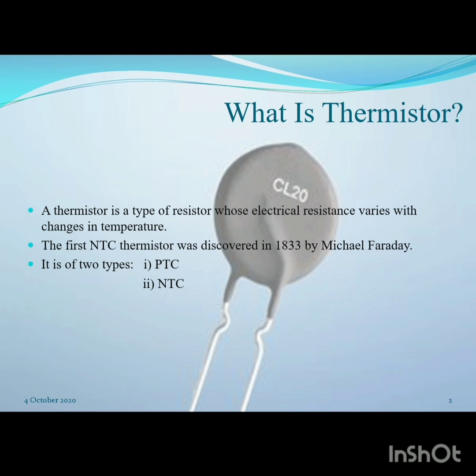A brief description of the PTC: resistance increases with a rise in temperature. It's just the opposite. This is the normal case for conductors. PTC thermistors are commonly installed in series with a circuit to protect against overcurrent conditions, as resettable fuses.